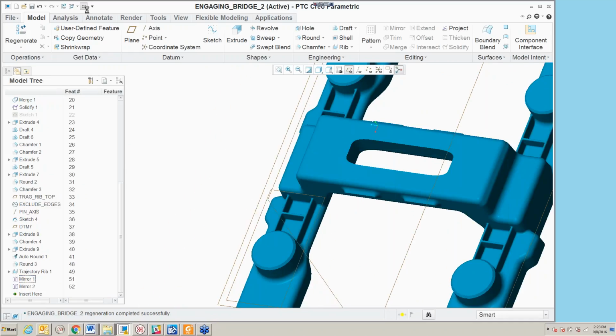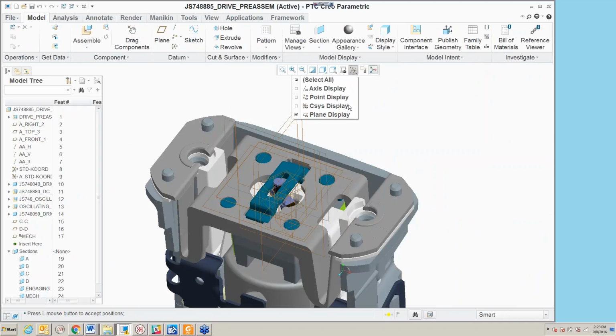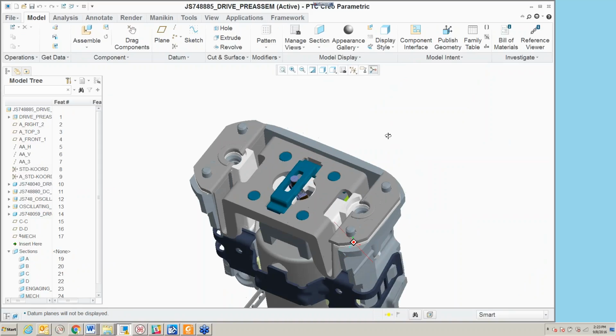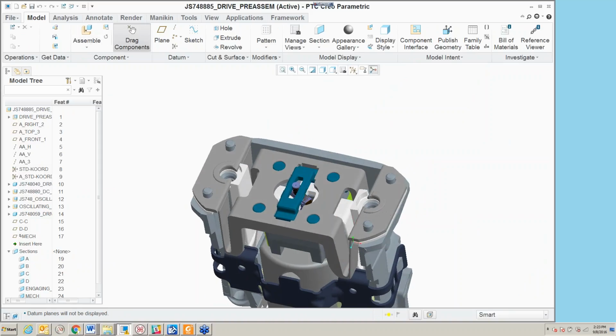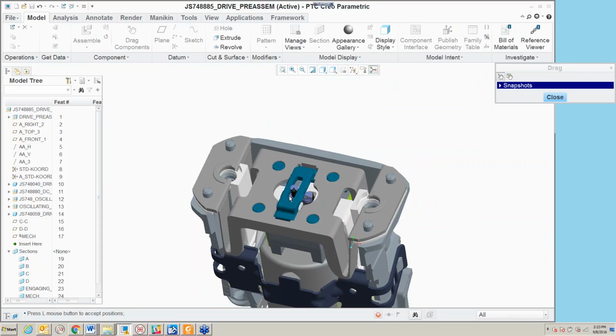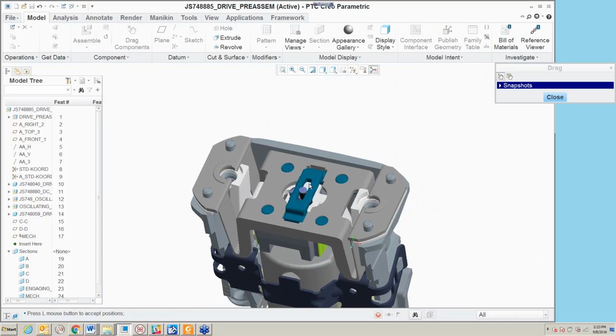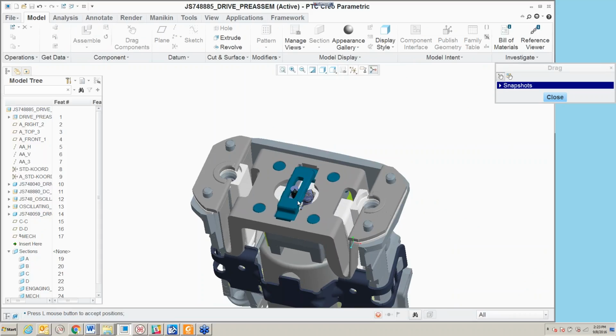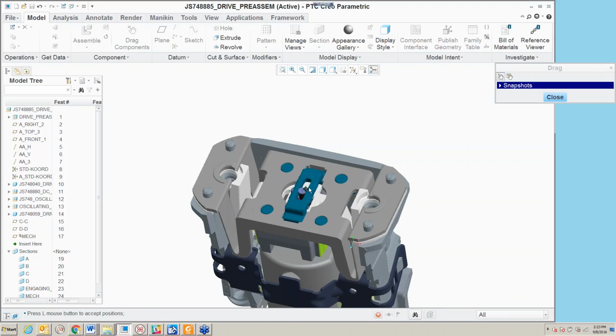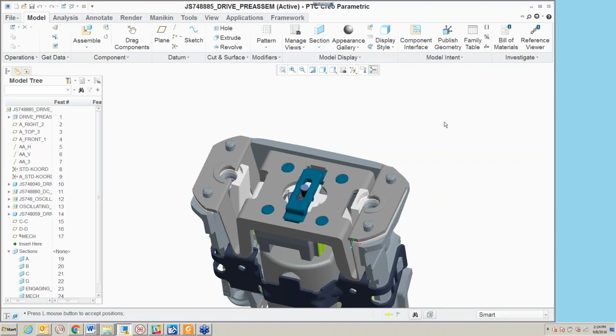of the geometry back, close out of it, come back to this window, let's turn off my planes, and now there's the part. Okay. And again, as soon as you make a change to a part and you come out of it, anywhere where that part is used, whether it's in an assembly or a drawing, subsequent objects are updated concurrently or automatically. All right, so that is just a quick demo of some simple part modeling.